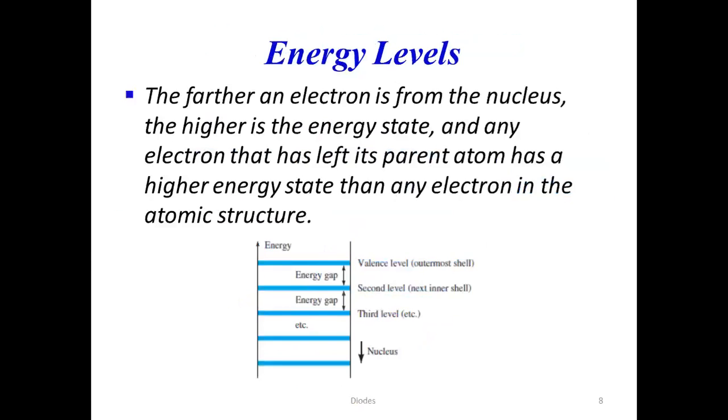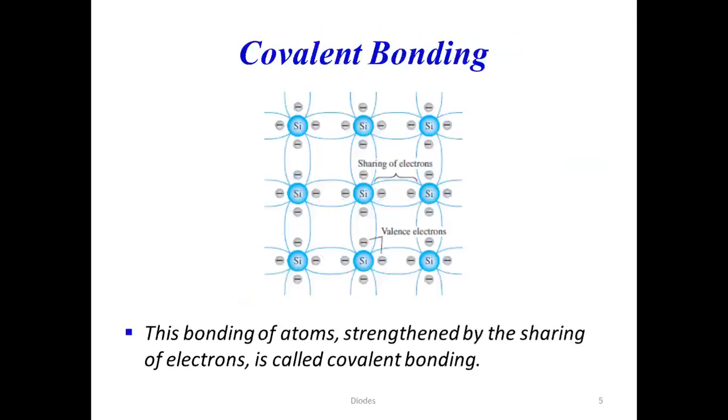Student, whenever I'm talking about the purest form of semiconductor, see here, if you see this structure, all silicon atoms are present. For every atom, there are 4 outer electrons in the outermost orbit, and they are making covalent bonds with other 4 electrons. So it is the purest form of semiconductor. All silicon atoms are there. If I add some impurity in the semiconductor, then it will become an extrinsic semiconductor.